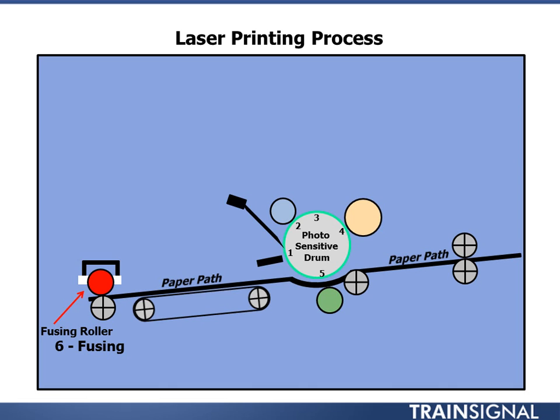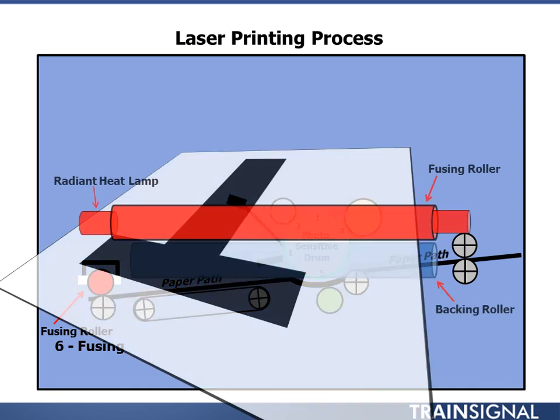Now, even though I will tell you, the fusing process very often is heated up to very extreme temperatures. You need to be very careful never to actually touch the fusing roller because we're talking about up to 200 degrees Celsius. That's way past boiling. This is scalding hot. Even though that's the case, the paper itself is not a material that's going to retain that heat very long. So even just in the time from when it's heated up, fused, and then spit out of the machine and sits in a tray waiting for you to take it, it's not going to burn you. But you'll notice it feels quite warm, especially if it's a cold day. Sometimes you grab it and it's like, ooh, warmth. It's kind of nice.